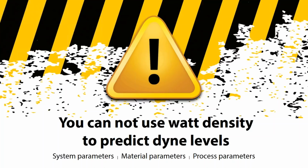I don't know. On average, in that example, could you get 56 dynes at that watt density? Sure. I think it's a reasonable expectation with that particular film and that particular condition. But I've also seen other examples with polyester films at similar or the same watt densities, and you don't get that dyne number. So really, trying to predict an end result, in this case a dyne number, using a watt density is not a good approach.